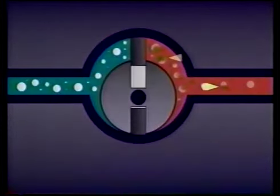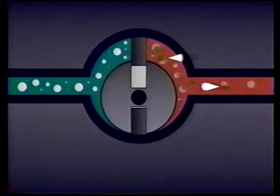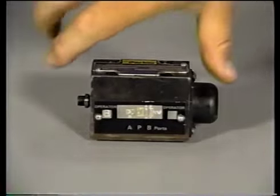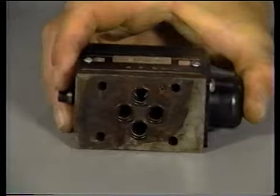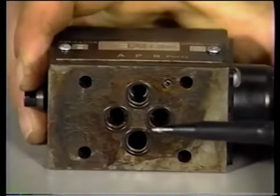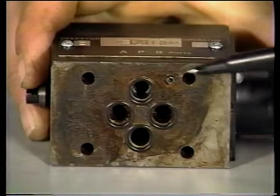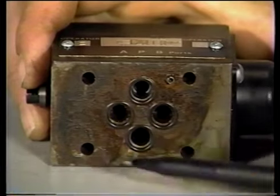This not only oxidizes the oil, but the collapsing bubbles create extremely high temperatures, which can actually fry the oil, forming resinous materials. The resins remain dissolved until they reach a hot metal surface, like a pump rotor or a valve. The hot surface will cause the resin to form a varnish that coats the metal surface. This varnish makes moving parts stick. The resinous material also forms a sludge that can plug up orifices and filters.